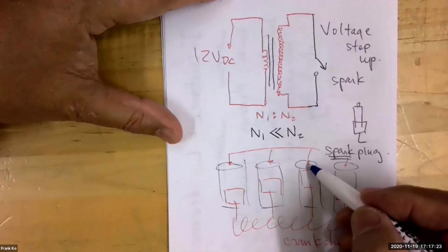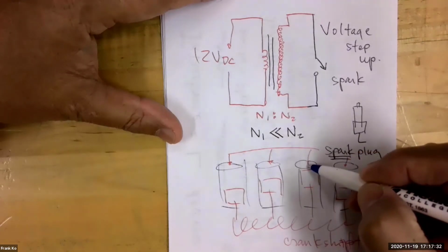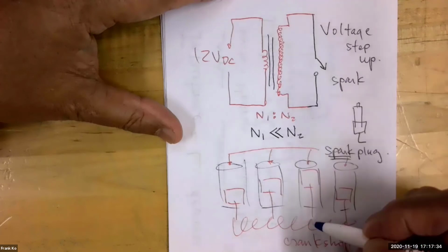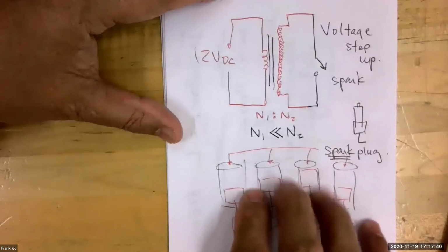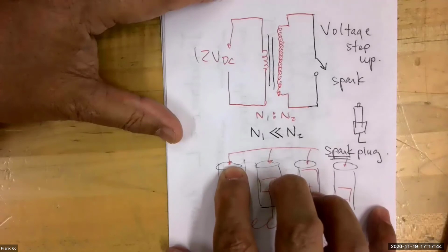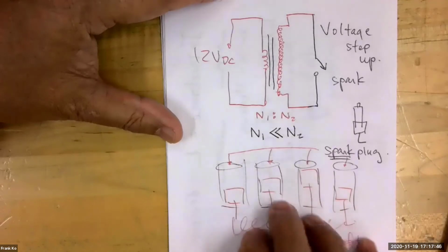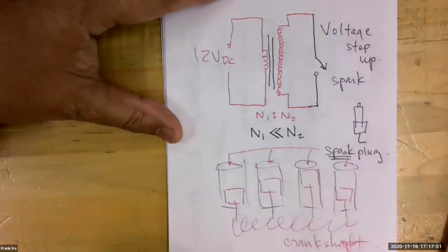And guess what happens when you light up a spark to gasoline? It'll do what gasoline does with a spark. It'll explode. And by exploding, it'll force this piston downwards. And as it forces it downwards, it'll help turn your crankshaft. And so as you get a multiplicity of these cylinders going up and constantly compressing gasoline and sparking to come back down, it turns your crankshaft, which turns your engine, which makes your car go.